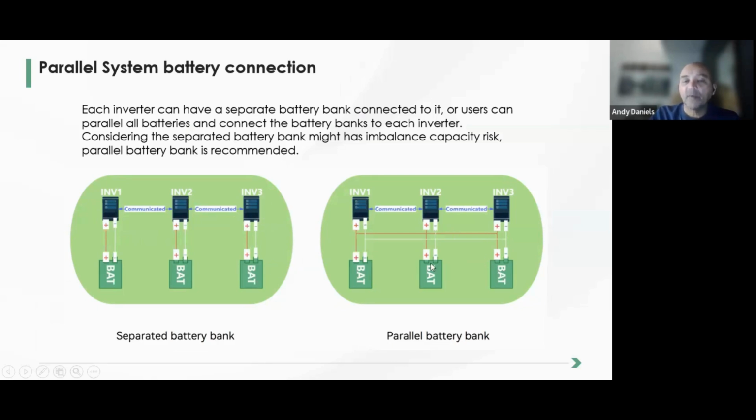In this particular setup, we have what's called a shared battery system with a DC bus bar. You can see the DC bus here. All of the batteries are connected to the negative on the DC and the positive on the DC. Then they will be daisy chained in their communication. So you will have one master, and all of these will be slaves, right? And then you have only the master battery talking to the master inverter. So remember that. In the independent case, you need to have 3 masters and 3 communicating to each inverter.